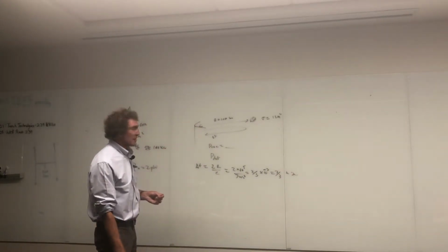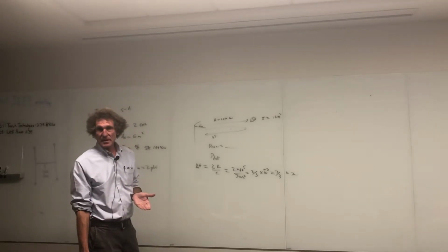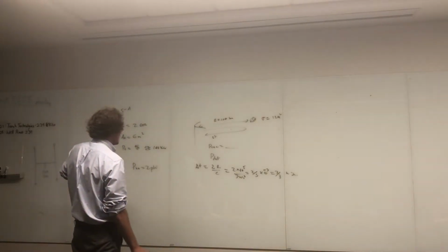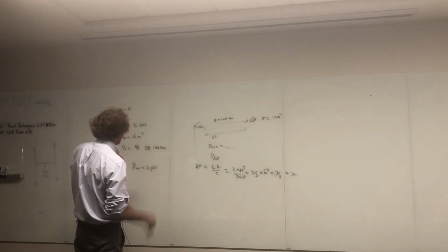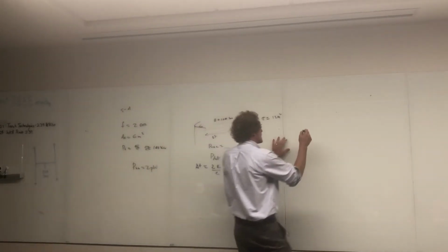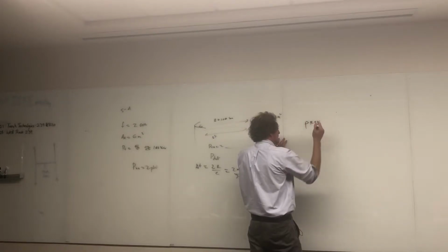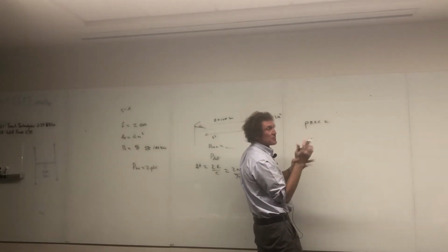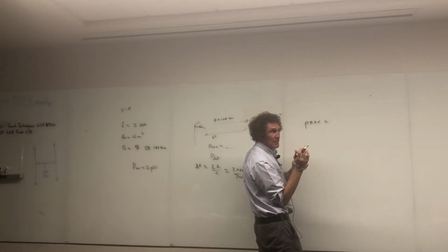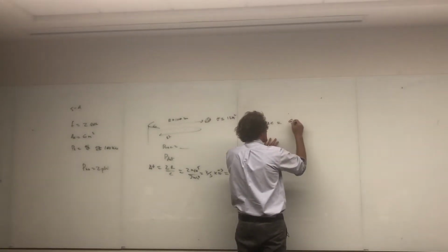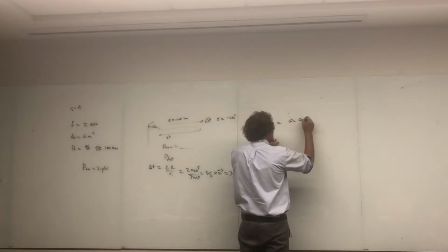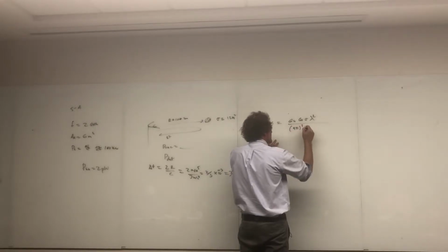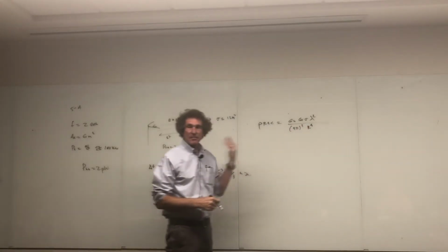Now that's the round trip travel time, a straightforward calculation: just the distance traveled divided by the velocity. The next thing they want is the received power for this problem. You can get P received a lot of ways. The simplest formula, if you want it all in one, is gain of the transmitter times gain of the receiver times sigma times lambda squared, on top, over 4 pi cubed times r to the 4th. That's one equation that takes care of everything.